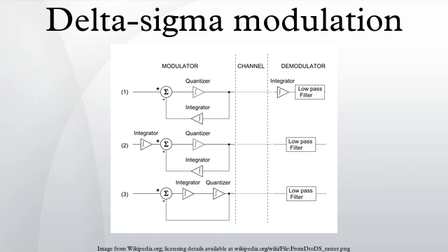One possibility for reducing this error is to halve the feedback pulse length to half a clock period and double its amplitude by halving the impulse-defining resistor, thus producing an impulse of the same strength but one which never butts onto its adjacent impulses. Then there will be a threshold crossing for every impulse. In this arrangement a monostable flip-flop triggered by the comparator at the threshold crossing will closely follow the threshold crossings and thus eliminate one source of error, both in the ADC and the sigma delta modulator.